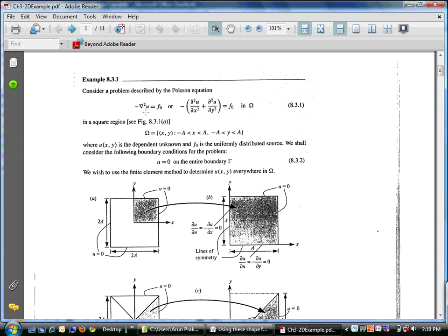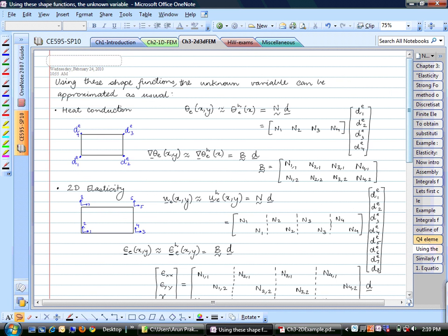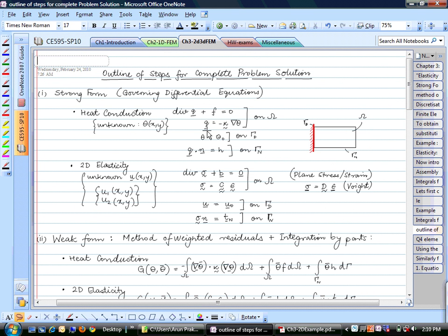Here U is supposed to be a scalar value, and this operator grad square is nothing but, if you go back to the lecture notes, and if you take this equation, you take this q, substitute minus kappa times grad of theta into this value here, you will get minus kappa, this grad square of theta, and you can assume that kappa is an identity tensor.